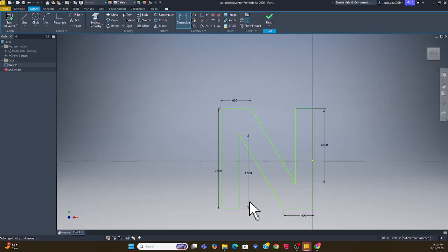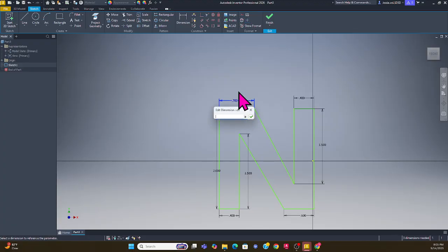All right, so I got that 0.6, 0.6. The only thing I need to worry about is the thickness here. Make this 0.4, and this is also 0.4. All right, check mark. Now, there are ways that you can make things equal, using any of these. If you want one segment to be similar to another, say I want this one now to be 0.7, and you can see this one's still 0.6, right? But first I need to get rid of this dimension first.